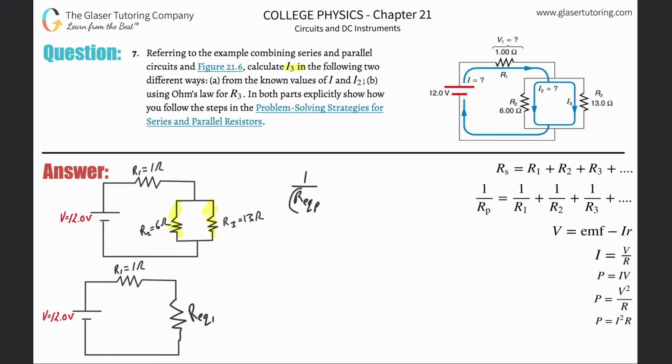In other words, 1 over the equivalent resistance of the parallel component is going to be equal to 1 over R1 plus 1 over R2. However many you have, it doesn't matter. Now, in this particular case, there's only 2 of them, right? Because I'm just focusing on that part of this circuit. So R sub EQ P is here, but I called it 1.